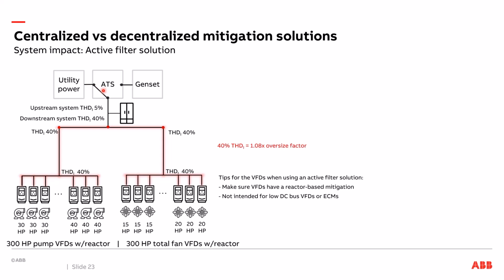Now let's do an example where, let's say, lightning strikes and it knocks out utility power, and also created a transient on the line that caused my active filter to trip out. So active filters have faults in there to protect themselves. Some of them auto reset, some do not. So if it's not an auto resettable one, somebody's going to have to come up and physically reset it on the unit. So lightning strikes, my active filter trips offline.